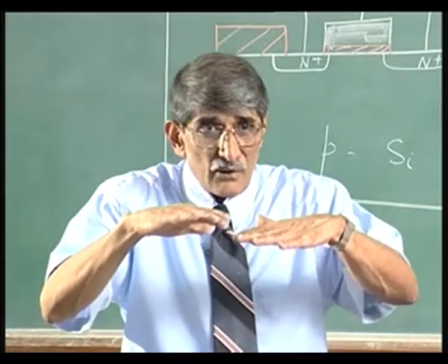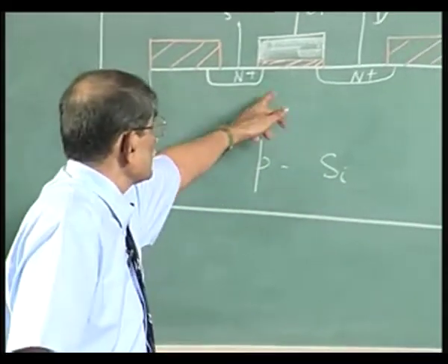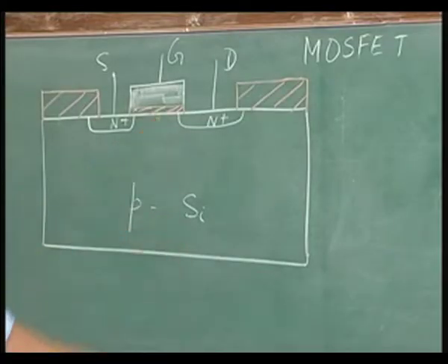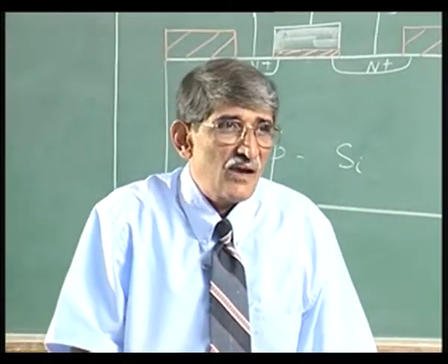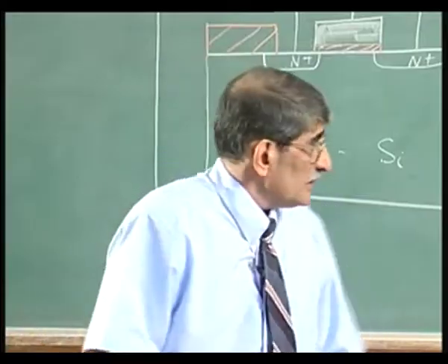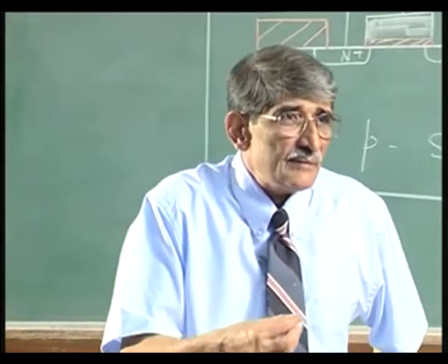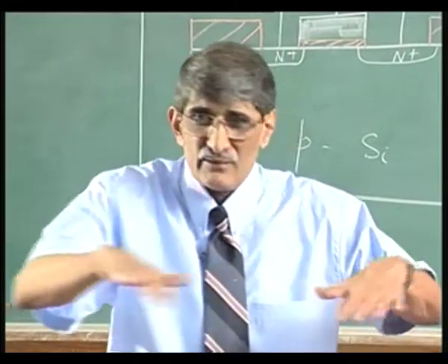Now, you oxidize that surface with the good native oxide. You do that, those dangling bonds are saturated with oxygen, silicon-oxygen bond. Okay. Immediately, you do not have the dangling bonds, and you remove those levels which I showed you, minimize them. There may be 10 to the power of 15 per centimeter square states on the surface.